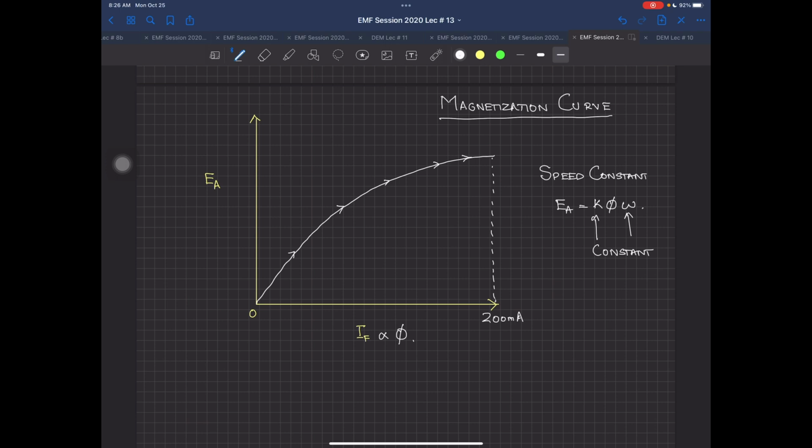So when they are aligned together, you cannot decrease the field current, because now you have to go up to the maximum point. Afterwards, when you start decreasing from 200 milliampere, you will have something like this trajectory being followed over there. If you go up till zero, this trajectory will be followed over here, and this curve will be called the descending curve.